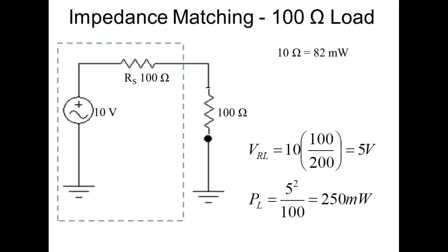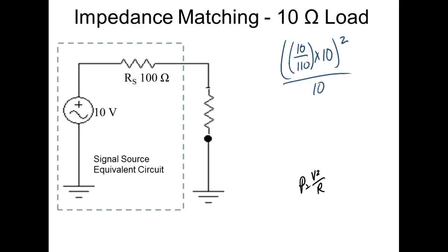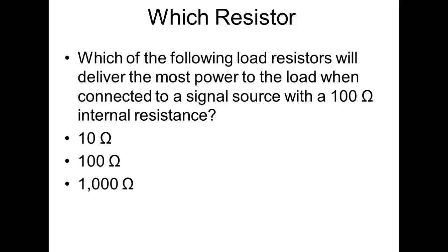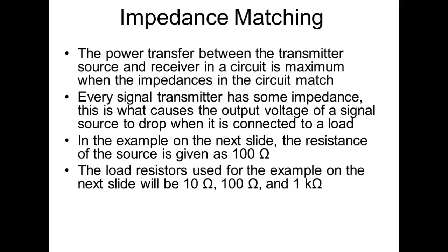So when the impedance matches in a communication system, what do you get? You get maximum power transfer from the transmitter to the receiver. So you take your car antenna off. It's got a piece of coax. It's got a coax wire running from the antenna down to the back of that radio. Have you ever pulled the radio out before? Well, what if you just hook just two wires up to your antenna? You just screwed up your what?